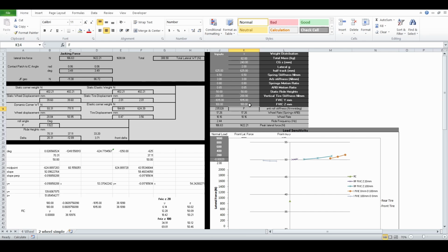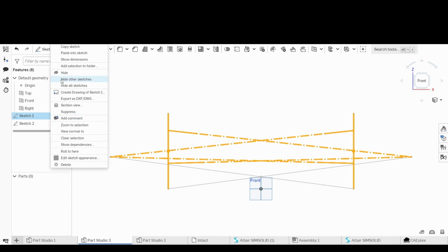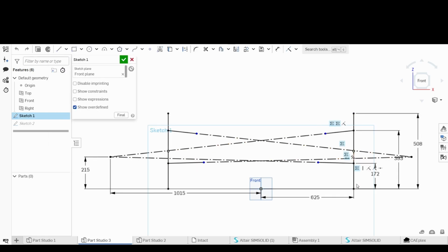try to remain consistent. All right, so now I'm going to show the difference of calculating jacking force through the A-arms, their actual locations, versus the end line. And all I did, I found the angle of the A-arms.